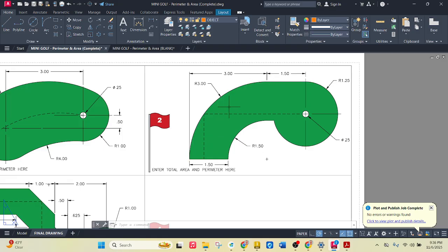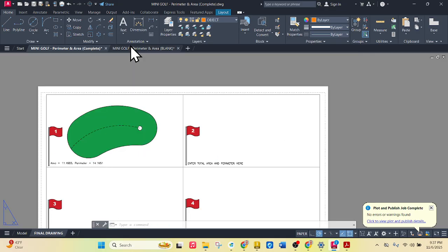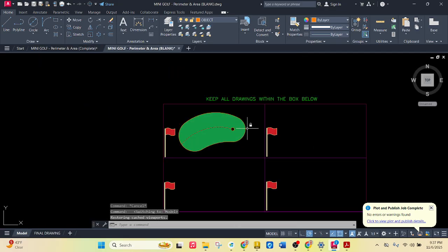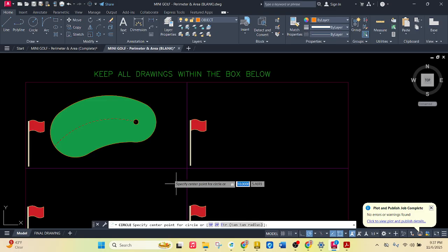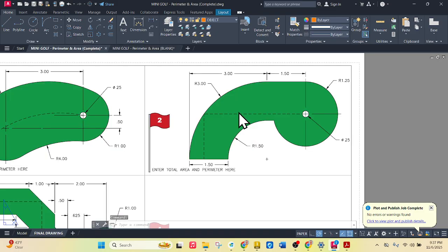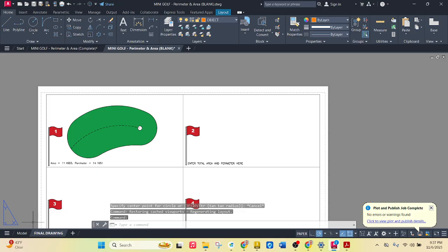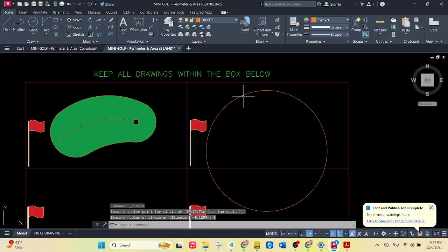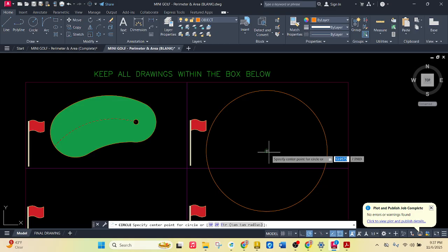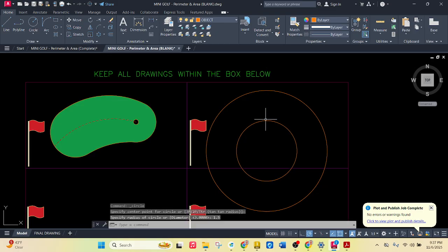and I'm actually going to draw 2 circles. I'm going to draw one that has a diameter of, or what we'll do with the radius tool, of 3 and 1.5, and they'll share the same center point, and we'll use that to build the rest of this. So back here, model, and I'm going to draw a circle with a radius, and I already forgot, it's 3 and 1.5. So we'll go circle radius, and this one is 3, enter. We'll do another one, and this one's 1.5, enter.